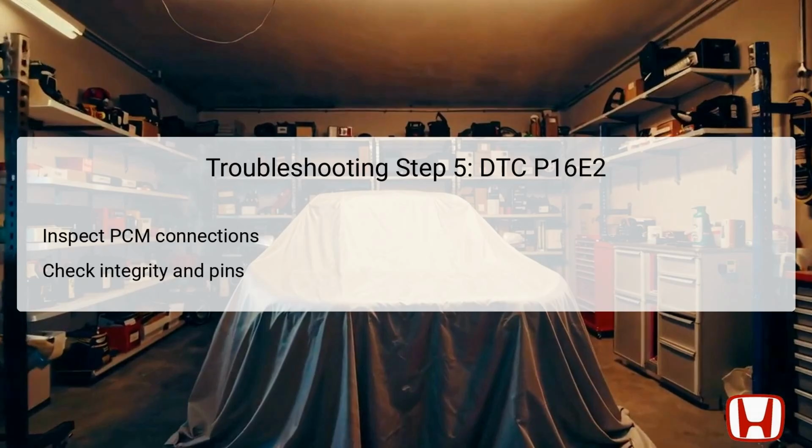Disconnect the PCM connector and visually inspect for any bent or broken pins, and apply cleaning methods as necessary to ensure proper contact. Should the examination show no faults, further testing may be necessary to confirm PCM functionality.